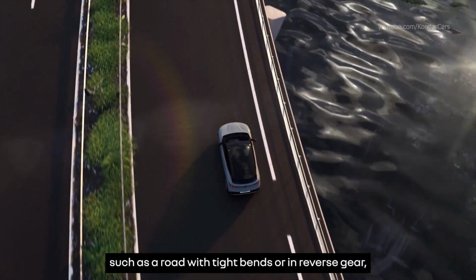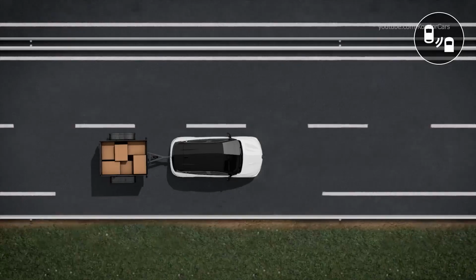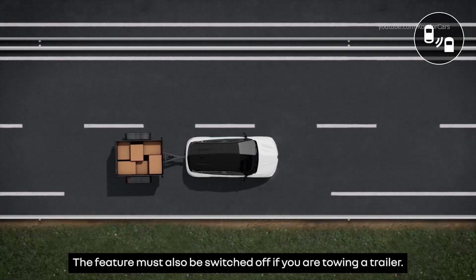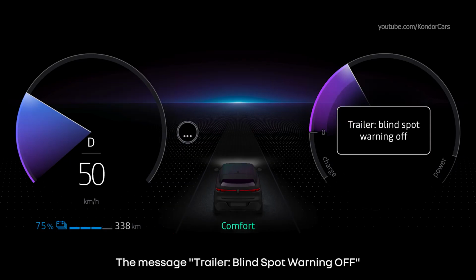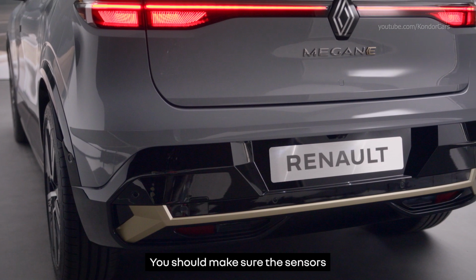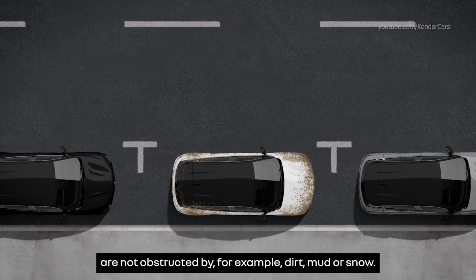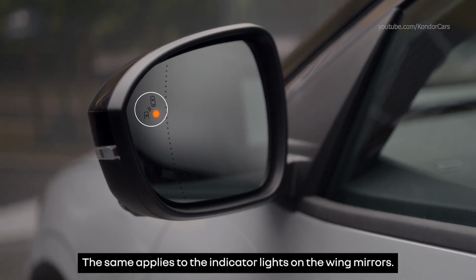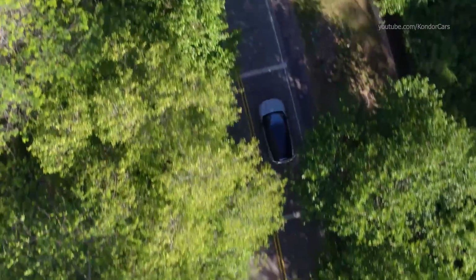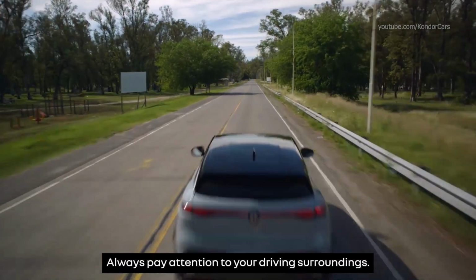In certain conditions, such as a road with tight bends or in reverse gear, the feature may be temporarily unavailable. The feature must also be switched off if you're towing a trailer. The message "Trailer Blind Spot Warning Off" is then displayed on the instrument panel. You should make sure the sensors on each side of the rear bumper are not obstructed by, for example, dirt, mud or snow. The same applies to the indicator lights on the wing mirrors. The blind spot warning driving aid cannot replace your vigilance as a driver. Always pay attention to your driving surroundings.